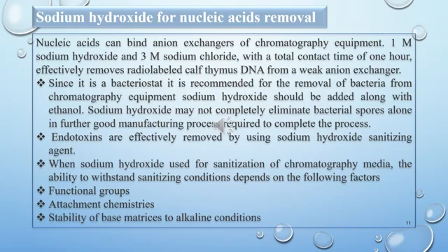Now, he said that we can also use sodium hydroxide for the removal of bacteria in chromatography equipment with ethanol. And the next point is endotoxins are effectively removed by the use of sodium hydroxide as sanitizing agent. Endotoxins can be removed from chromatographic equipment by using sodium hydroxide as sanitizing agent.